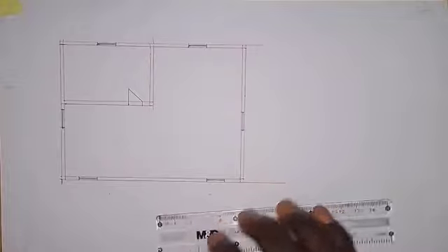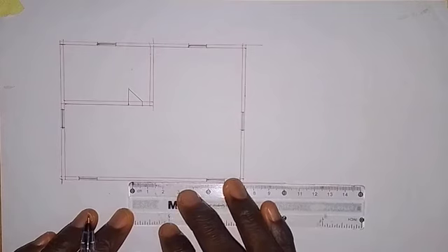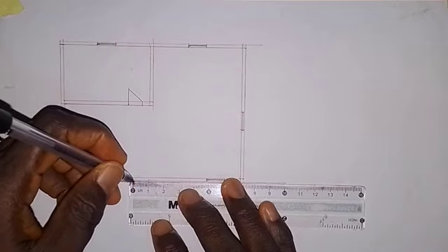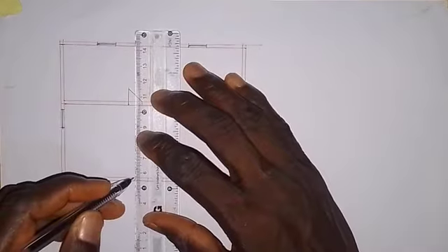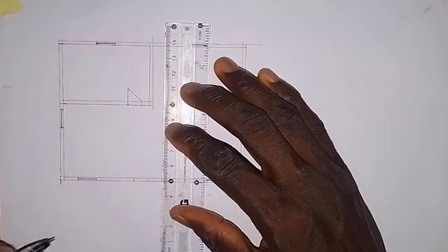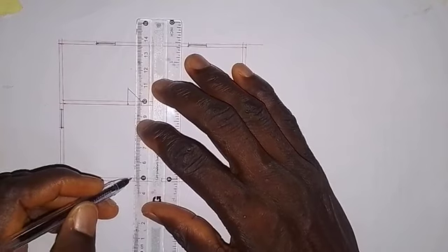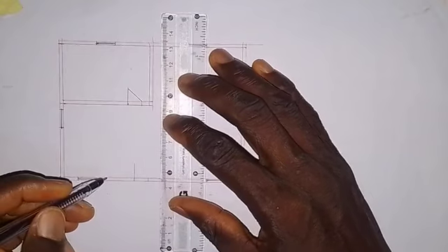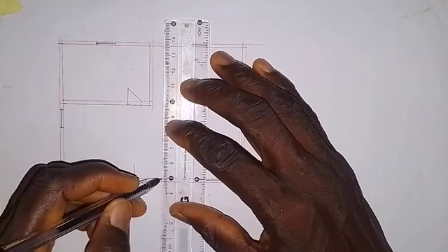So now, for the entrance door, we have the two doors. We have the doors within this space here, in the middle. So all I have to do is put a mark here like this. Okay. Take 9 millimeters to this side, and then I will take 9 millimeters to this side. All right. Then I'm going to draw a line here. I will also draw a line here. Then at this point here, I'm going to draw a vertical line 9 millimeters up here like this. And coming to this side also, I will draw a vertical line, 9 millimeters up. So it goes up like this, 9 millimeters up.